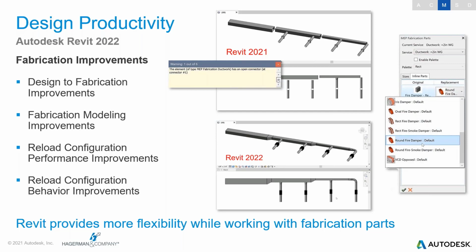Right. And then the design to fabrication tool is more flexible in this release, enabling mapping of solutions during the conversion process from Revit families to fabrication parts. You can connect fabrication elements together in Canvas by dragging connectors. As with design parts, now the fittings will be placed. So there's more consistency with layout tools such as Quick Connect, Route and Fill, and Trim and Extend.